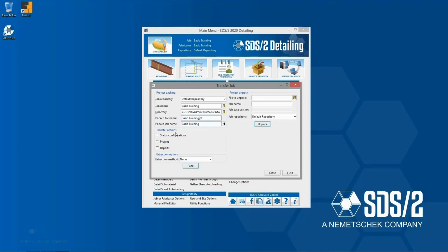job. Transfer options allows you to include information from your default directory like status configurations, plugins, and report files. This would be if you're providing to someone else off-site and you're not for sure if they have the same plugins and information for this version you're using. The extraction options allow you to use a drawing reduction, which just helps reduce the overall size of the project, so it only be used for backing up the project.